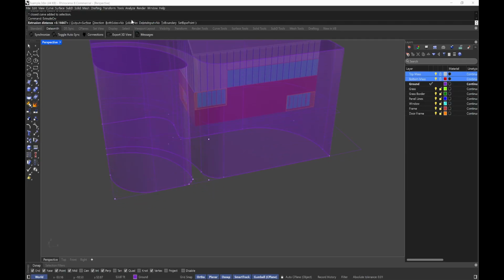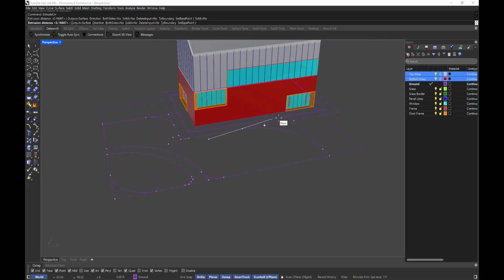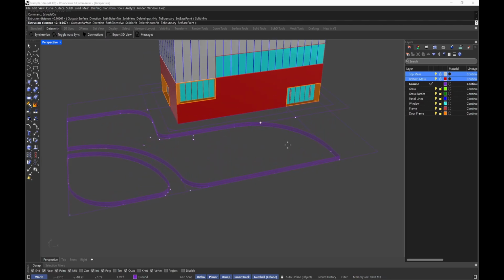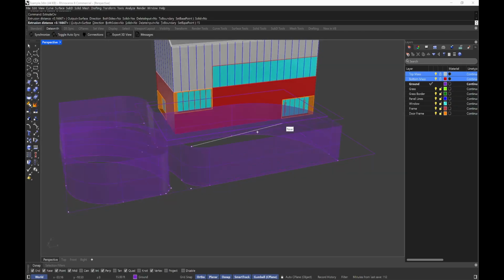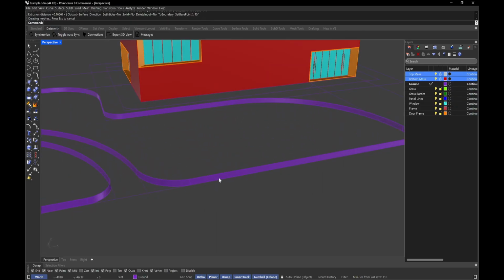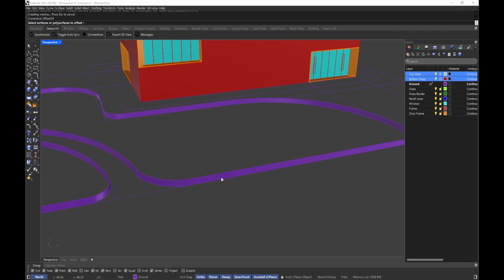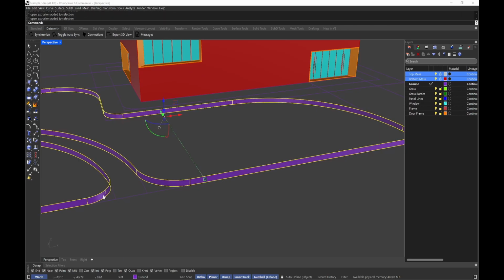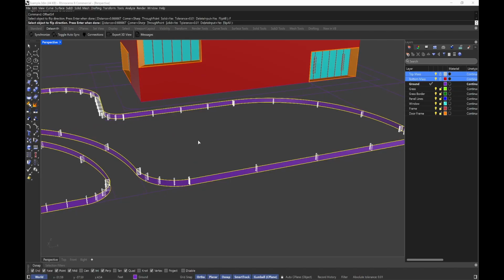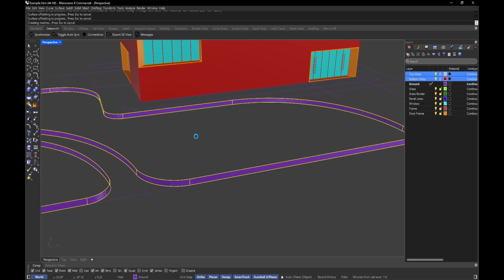And I actually do not want it solid. I want it like this, right? Let's think, we can do curb edge height, or I'm thinking more of this, because this is maybe an institutional building, so it's more bench height. People can sit on the edge, more of an urban context. So let me go up maybe 15 inches, right? And then let me select these first and then do offset surface. Let me flip the direction so it's inward. Maybe we can do 12 inches, 9 inches. We'll do 9 inches. There you go.